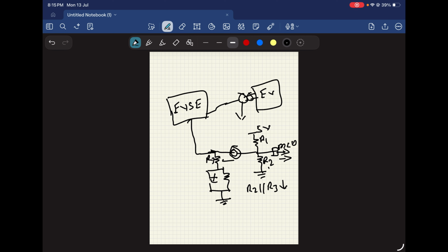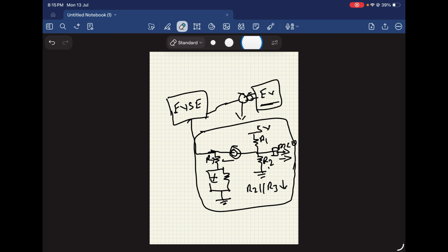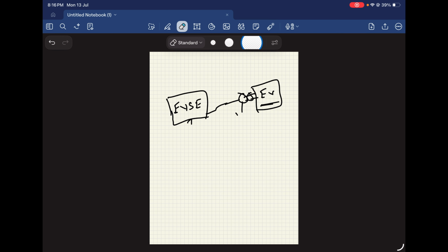After that, it is properly connected. Why is this required? To verify whether the charging station connector is properly connected, the electric vehicle verifies through this PP line. Once it is verified that it is properly connected, then it will go to CP. How will it work?